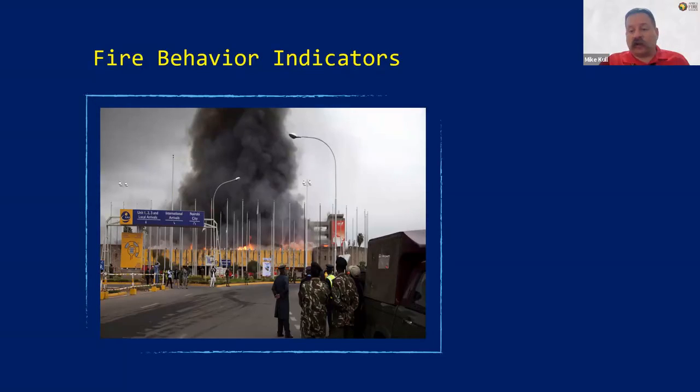We're looking at the flow path, okay? Any fire needs to be fed. It needs heat, fuel, and oxygen. That oxygen is coming in through some sort of an opening. Wherever that fire's drawing air, drawing oxygen into the building, that's the intake flow path.